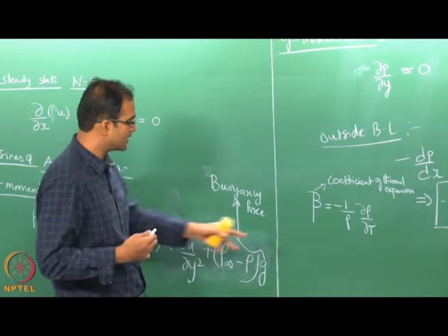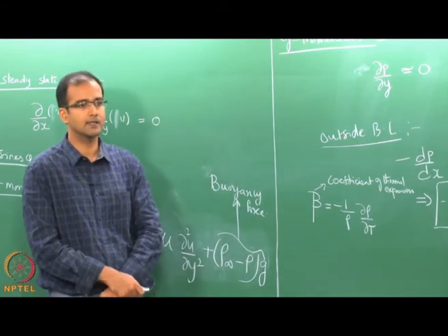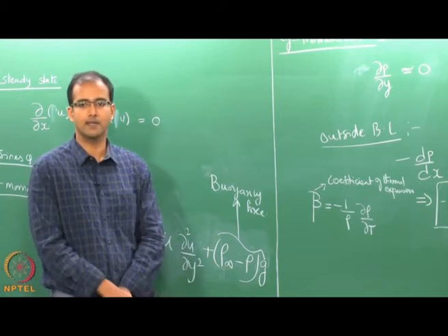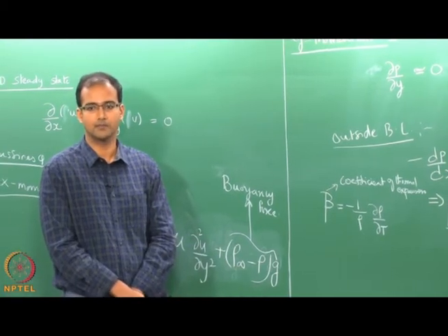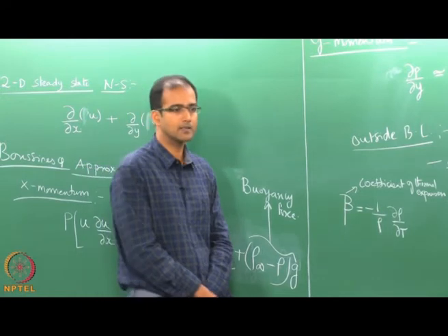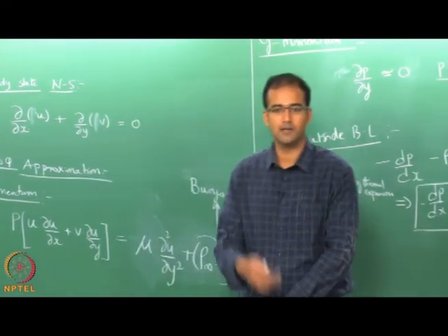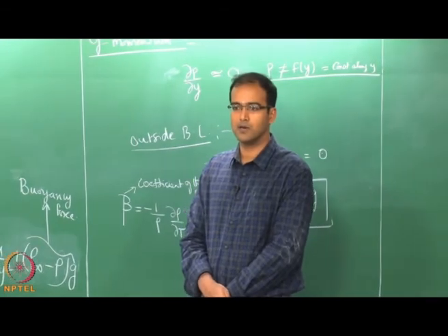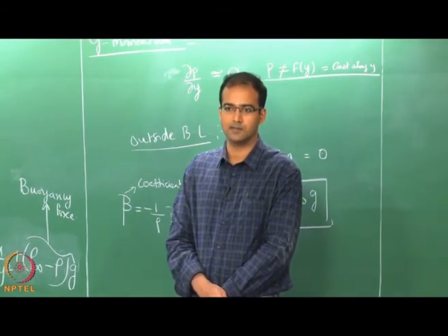So, the higher the value of beta, the higher the potential for density difference. These are usually measured as part of the thermophysical properties, just like thermal conductivity and specific heat capacity, and they are tabulated for different gases.